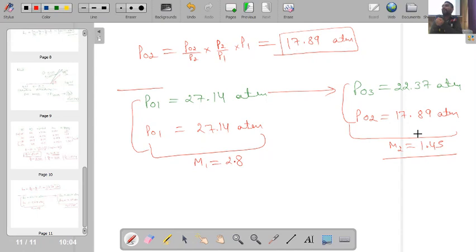So in order to have high propulsion efficiency, if we have to decrease the Mach number, if we have to slow down the flow in certain situation, it is always preferred to use the combination of incident and reflected shock waves, because this process of decreasing the flow speed will give us better propulsion efficiency. Why?